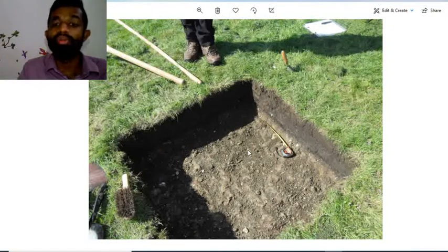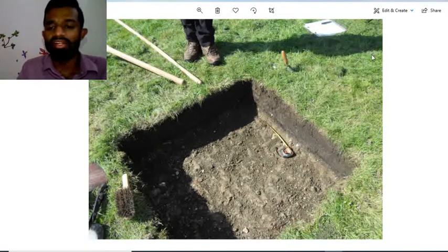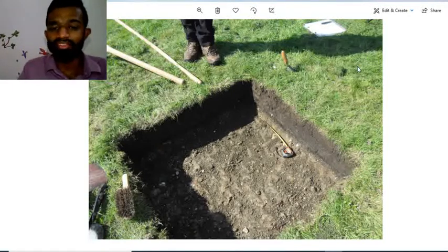If there are various types of layers, he will analyze them, and he will assume a bearing capacity for the existing soil in your land. If it's dumped or filled land, he will propose a special method to excavate it, refill it and compact it well, and he will tell you the depth to place your foundation bottoms. It's very crucial, because your entire structure will rest on these foundations, and the foundation will rest on this